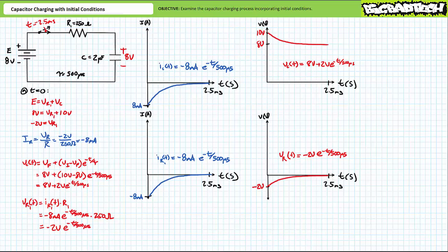During a charging process, current rushes through a resistor and into a capacitor, while charging voltage across a capacitor rises. During a discharge process, current rushes out of the capacitor and through a resistor. While discharging, voltage across the capacitor drops. Any voltage experienced by a resistor is simply a consequence of the incoming and outgoing current experienced by the capacitor during the charge or discharge process.